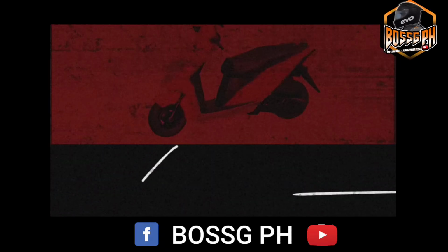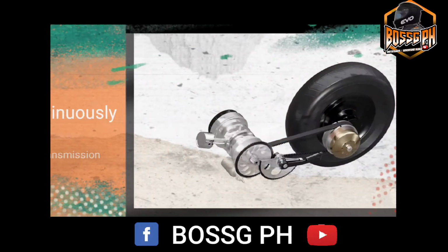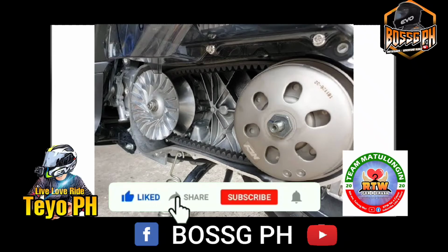Scooter is one of the most common two-wheelers popular in many parts of the world. They are typically equipped with an automatic transmission system. This transmission system is known as continuously variable transmission, or CVT. The basic principle of a pulley-based CVT can be demonstrated by using this simple setup.